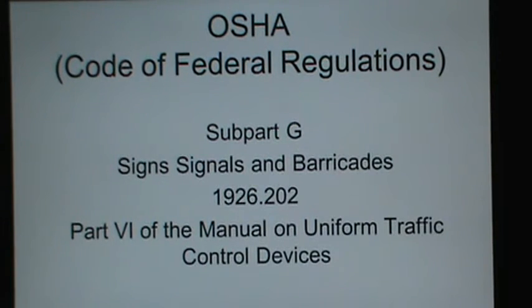The next thing we're going to talk about is in paragraph 202, which is barricades. Barricades for the protection of employees shall conform to what? Part 6 of the Manual on Uniform Traffic Control Devices.